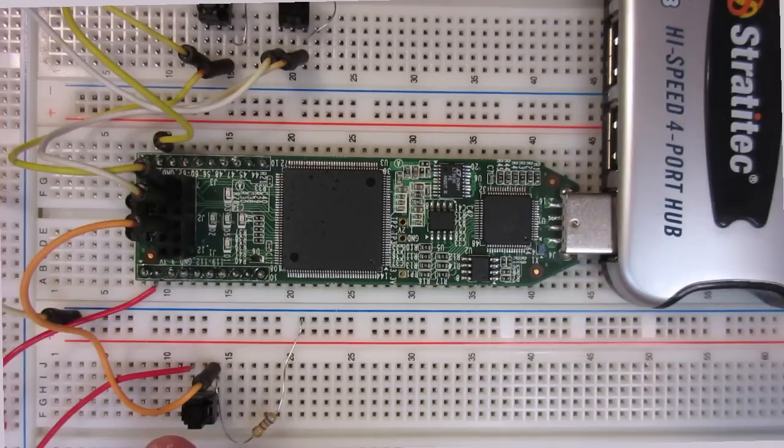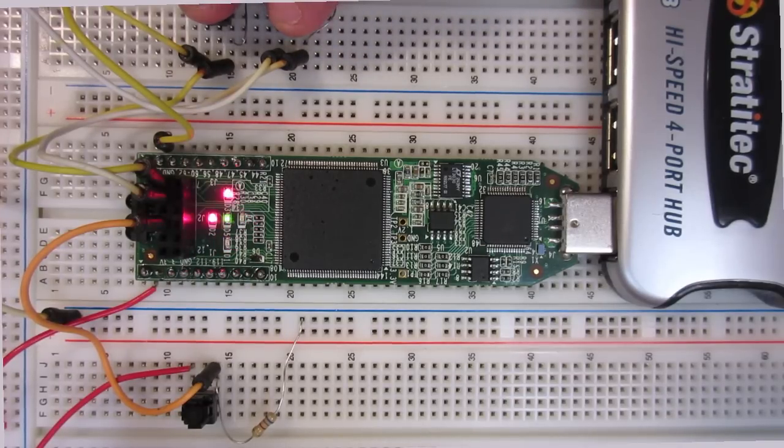So the thing we really want to test is the adder. And for that we're going to go to the buttons up at the top, the A and the B button. When you set one of those buttons on, that's going to put a 1 on the device, and the sum of 1 and 0 is going to be a 1, so that LED lights up. D1 down there at the bottom is the sum. Now if I go to the other input, now I've got 0 plus 1, which is still 1, so I get the same result. If I put both bits to 1, I'm going to get a carry of 1, which is D2. The sum is 0, and I also light up that top LED.